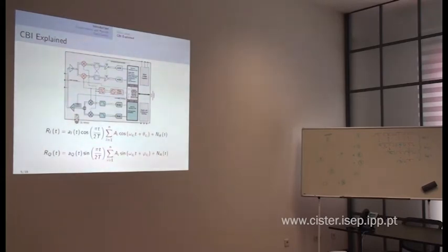Now you don't have a carrier frequency at the output of this. What you have is baseband. If you multiply this signal by this synthesizer, in frequency space it brings you back to zero, if these two frequencies are the same. The problem is that if you look at this equation with n equal to 1, you have a single harmonic function, and that's fine. That's how the radio normally operates. But if you have n transmitters, then what you get here is a superposition of harmonic signals with slightly different frequencies.